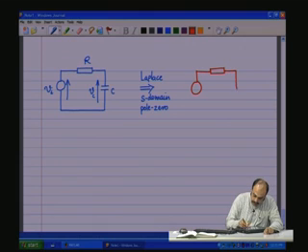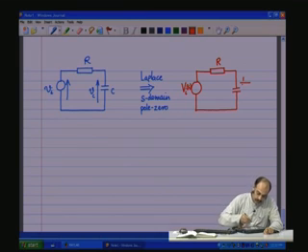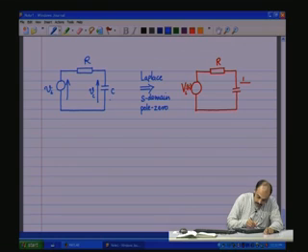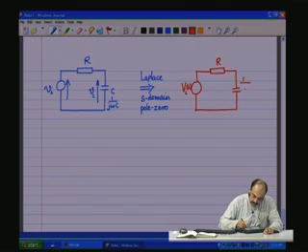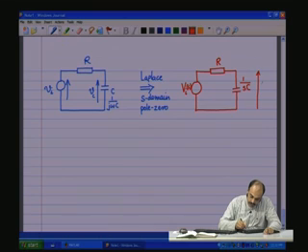We have the R, C, so we have Vi which is now a function of S. Lowercase v has been converted to uppercase V, R remains as R, C will result in, here it was the reactance which is 1/(j omega C), and here it will result in 1/(SC), and the voltage across C is now capital Vc, a function of S.